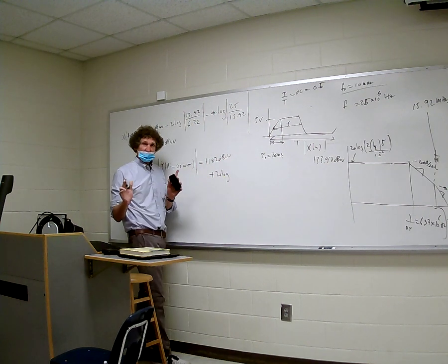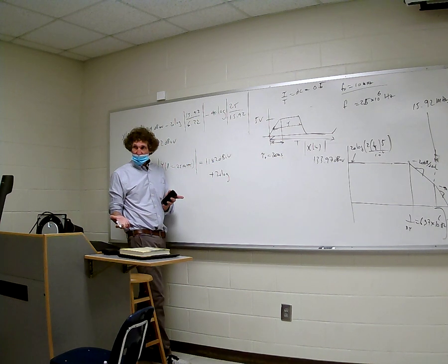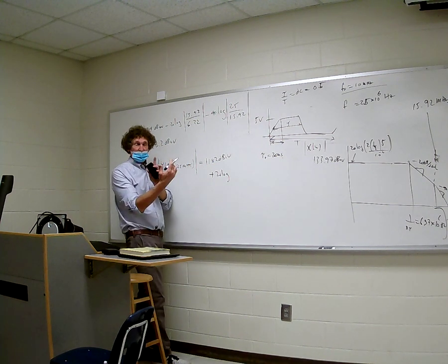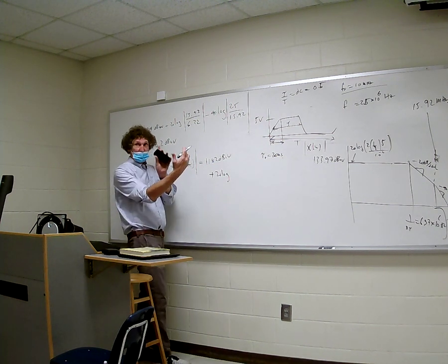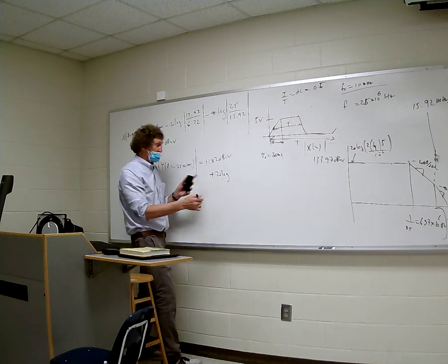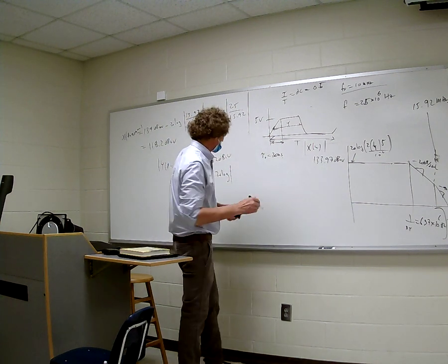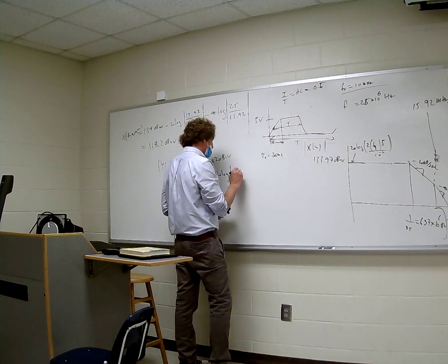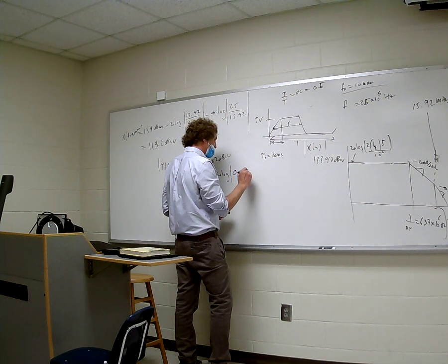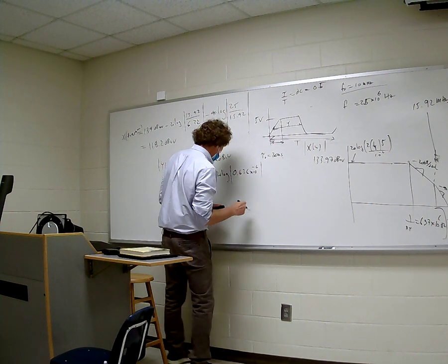There's a plus there because with the filter you don't know if it's going to increase or decrease, right? When you multiply x times h, it's log of x plus log of h, and there's a 20 in front of it, so it's 20 log of h. And h is, what is that again, 0.636 times 10 to the minus 6, right? Yes. All right, go ahead and do that.